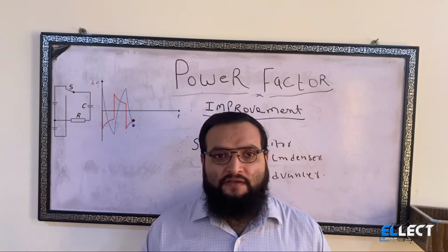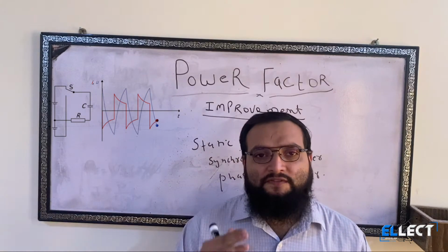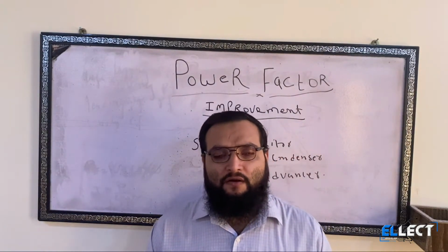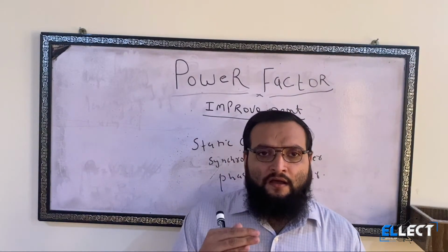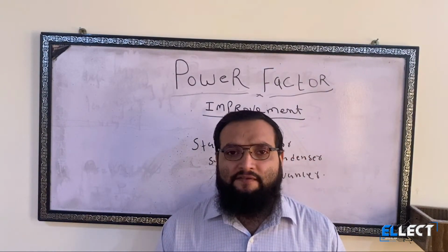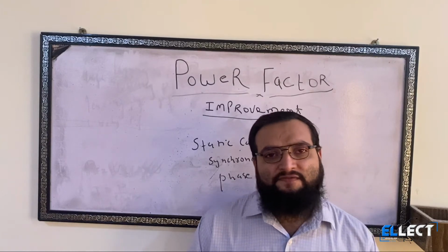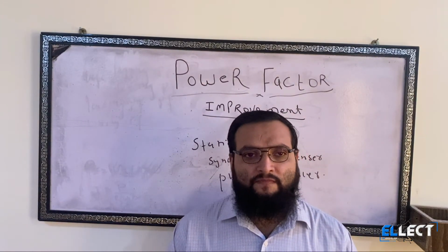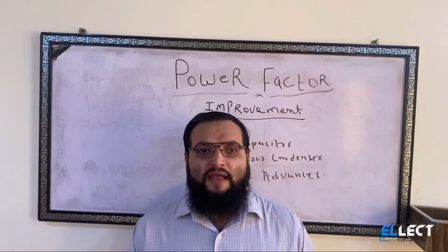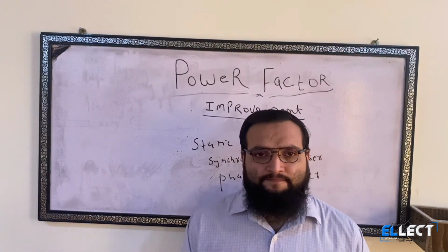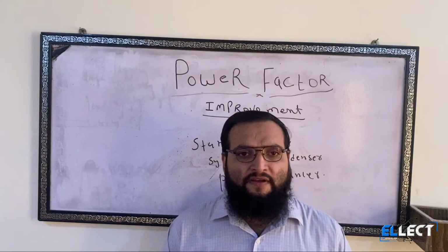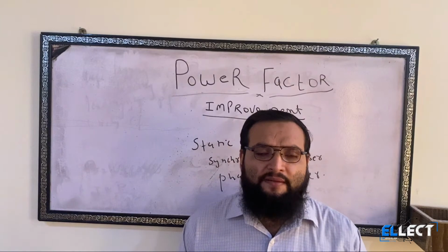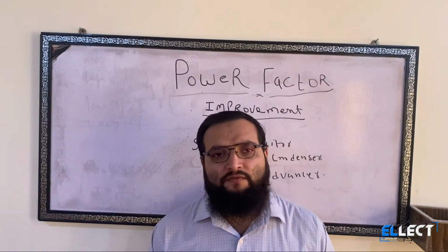When the static capacitor is connected in parallel, it causes the leading component of the current, which neutralizes the lagging component of the current, approximately or totally. That will be defined according to the efficiency and the conditions of the lagging component. And whenever the leading component of the current increases, it equalizes or eliminates the lagging component of the current of the load.